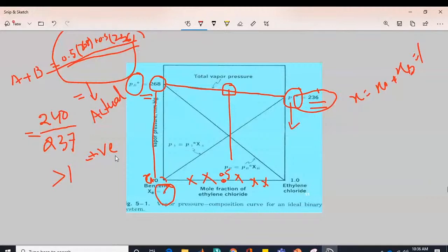Even with mass transfer, we always talk of surface area, contact area and contact time. If you give it more surface area and more contact time, there will be higher mass transfer. Similarly for heat transfer. So these are nothing but a way to provide contact time and surface area between two phases, vapor and liquid. The more time they have, the higher the chances of condensing that vapor.